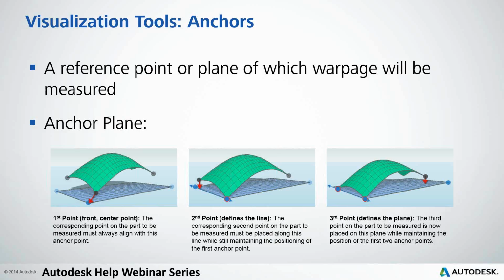So if you have a critical dimension, say, on an edge of a part, then try to align it that way, because then it'll orient the deflected part to that direction as well. The third point then creates kind of a plane so that you can measure off of that point for other measurements also. And it just kind of constrains it loosely there, just, again, orientation-wise.